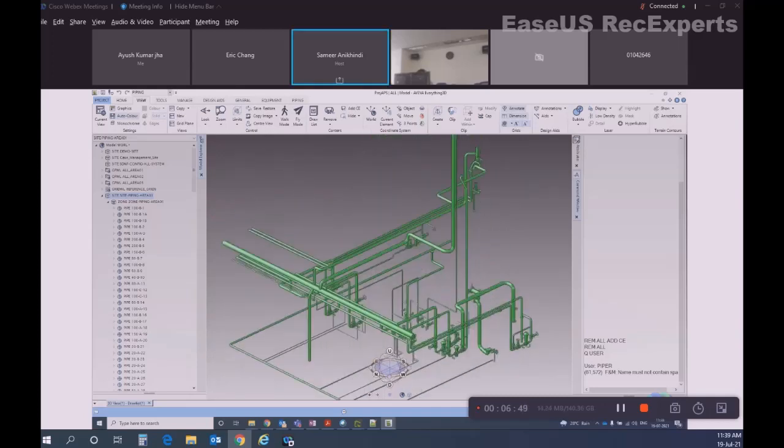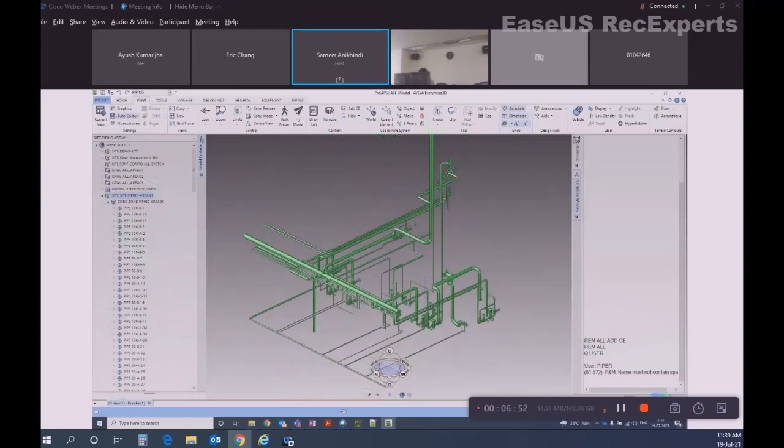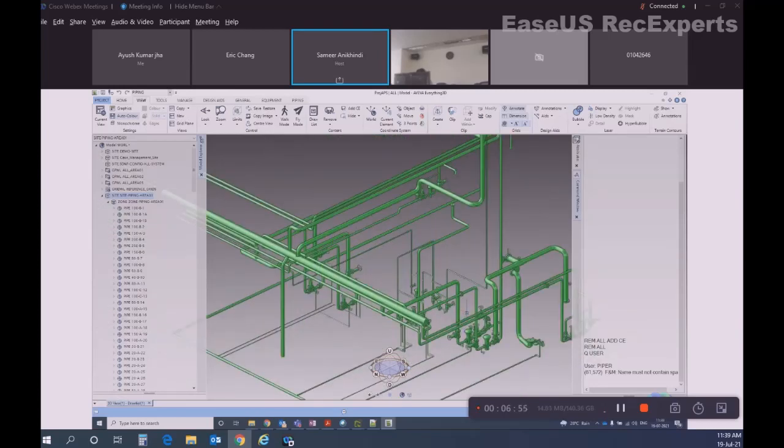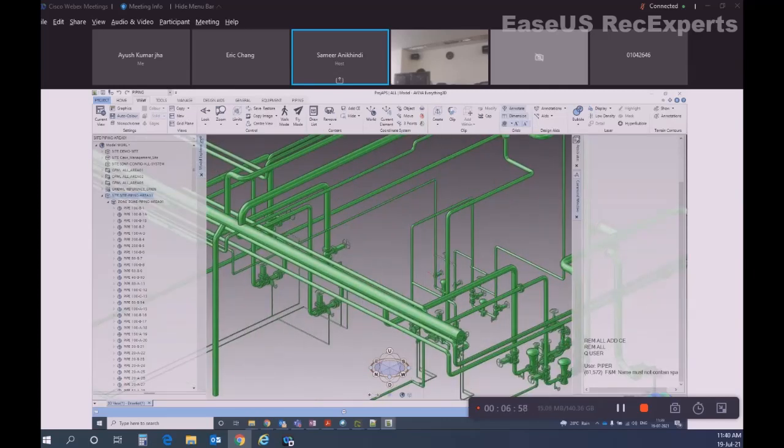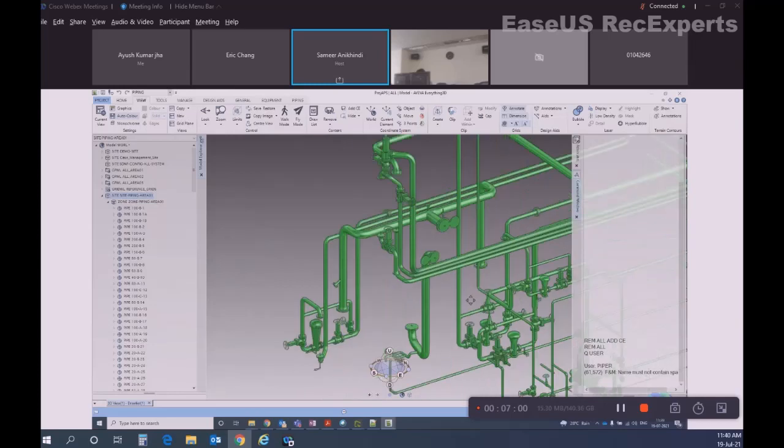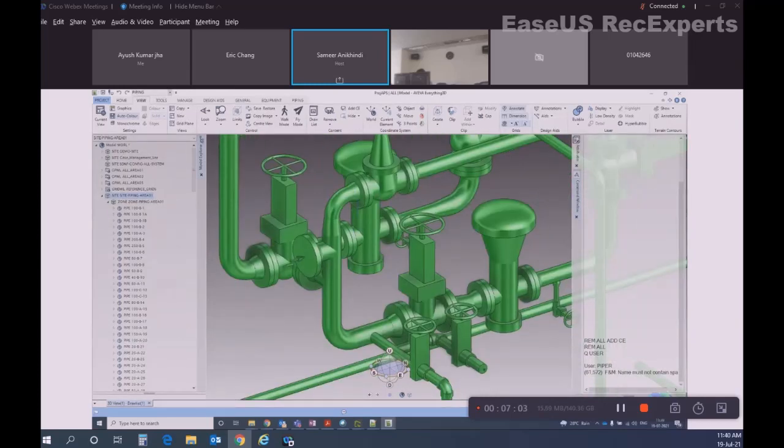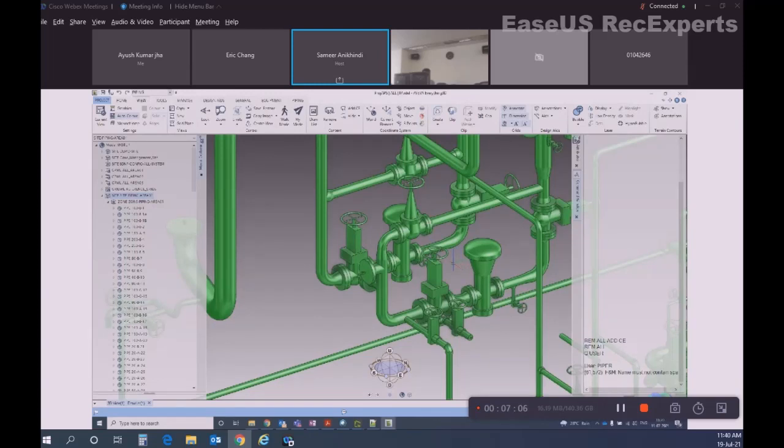Now you can see the pipes are there, but some pipes might be insulated, but it is not being shown. Or some components might have some obstruction volume. What is obstruction volume? Obstruction volume is a soft volume, not actually a physical volume, but required for operation. For example, valves have a hand wheel going up and down, so you want to reserve some space so that nobody else can model in that space. Those are called obstruction volumes, which are detected in clash, but normally are not visible.